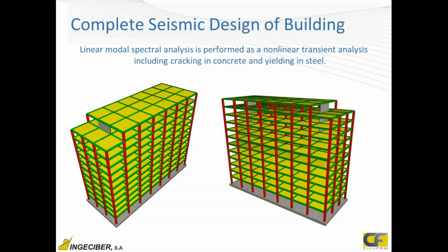We'll start with a linear model spectral analysis, where we can take into account the typical codes and the standard loads applied for buildings, as in Eurocode or ACI code, with their typical combinations of forces and loads, and we will check and design the reinforcement of these elements for slabs, beams, columns, and floors,